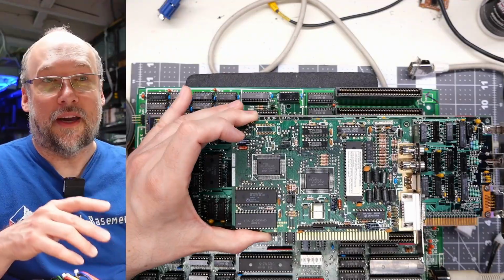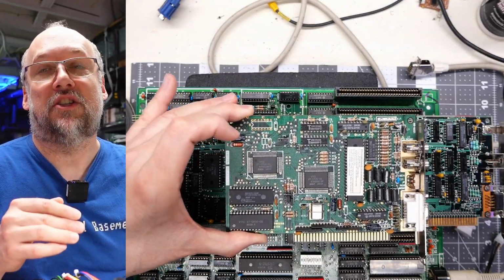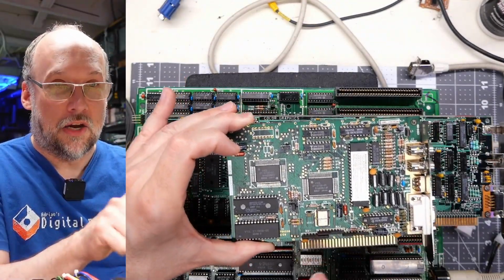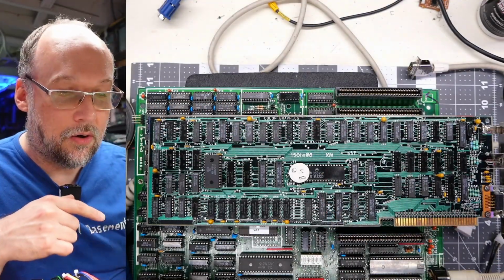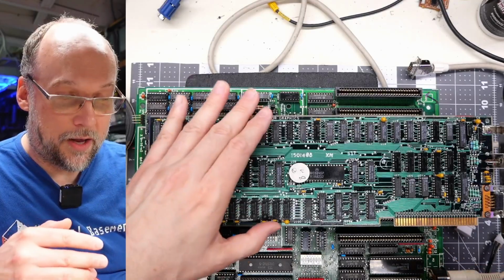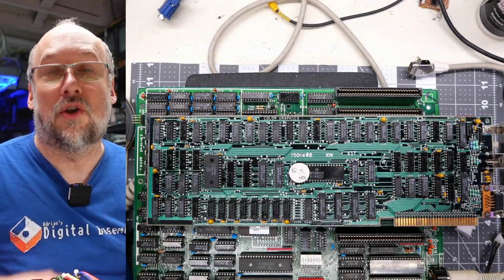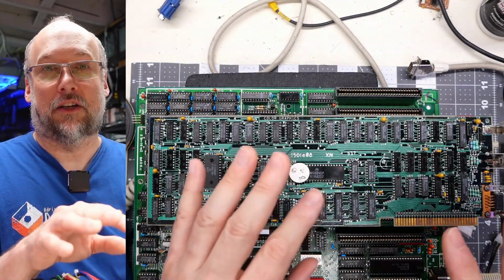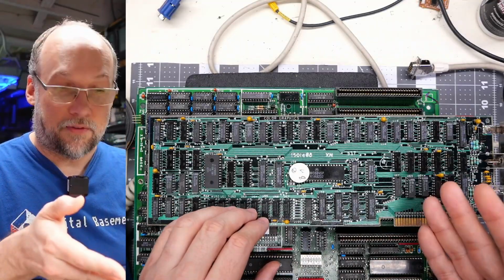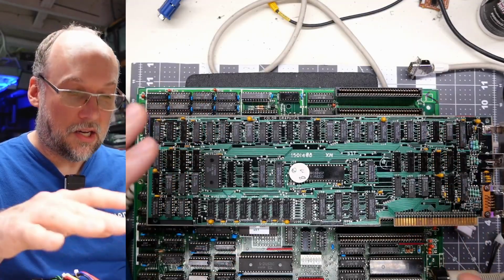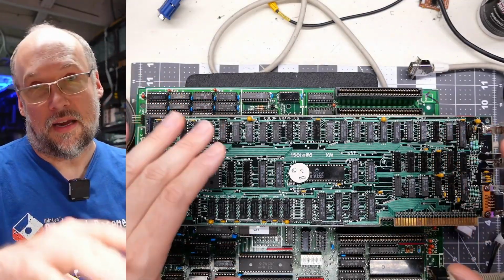And if you run any applications that test for snow, like Jim Leonard's CGA compatibility suite, you won't get any on this card whatsoever. But with this card, I demonstrated in the last video, anytime you're doing the RAM access while you're in 80 columns mode, you're going to get this whole snow pattern. And depending on how much access there is, it can actually cover a lot of the screen. Now the 40 columns text mode and the graphics modes don't have the snow issue. It is really only a problem in the 80 column mode.